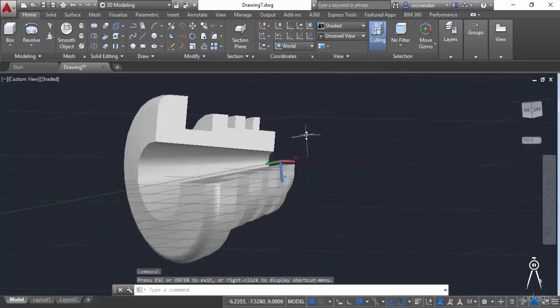Let's orbit it. In this way, you can use different kinds of geometries for making a revolved 3D shape. For that you can use other geometries like arc or spline as well, but the condition is that the geometry needs to be completely closed. In the next section, I will tell you about the sweep command of AutoCAD.